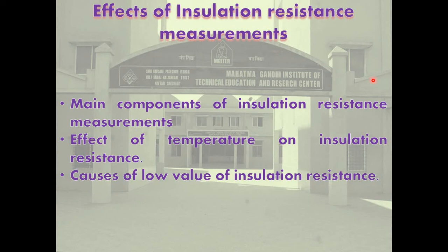In an oil immersed transformer, the temperature of the top oil is taken as the insulation temperature, while in dry type transformers, it is the ambient temperature that is taken as the insulation temperature. The result of the insulation resistance measurement should be checked against the manufacturer specification or against the result of the previous test. If there is no such data, the check should be made against the value specified in the standards.